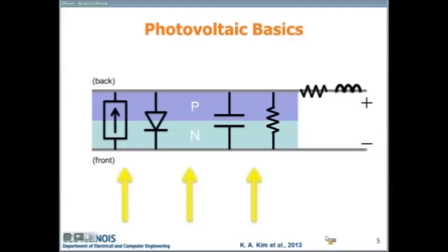Okay, so this is the model I'm working from, and one thing that's not captured in this aspect is reverse voltage, which is the key to hot spotting and understanding what can happen when the cell gets compromised. But if you reverse, you can just think of it as a diode. If you reverse, they have that breakdown voltage on a diode, right? If you go above that reverse breakdown voltage, it will act like a zener and go through. So that's the last part that we'll talk about.